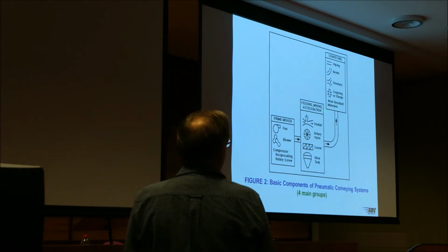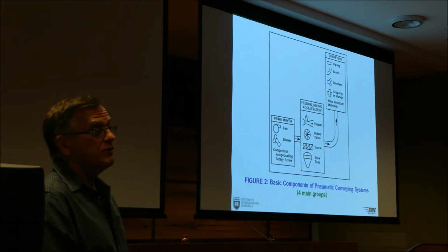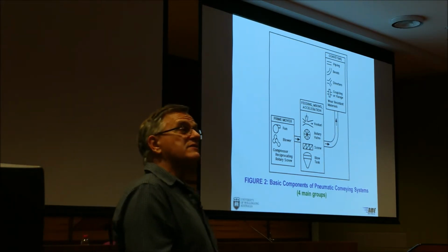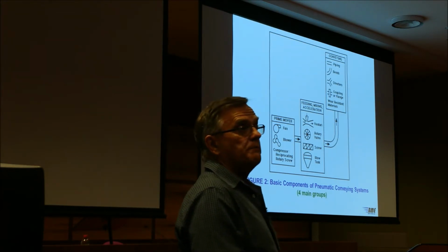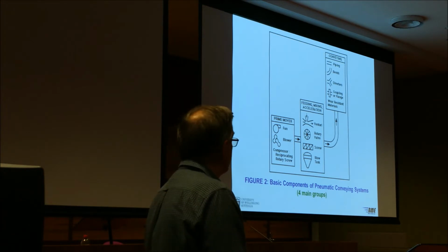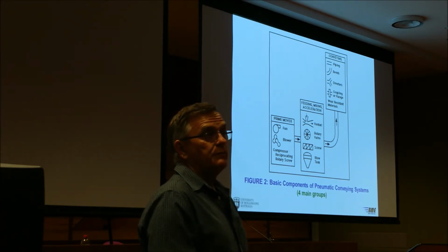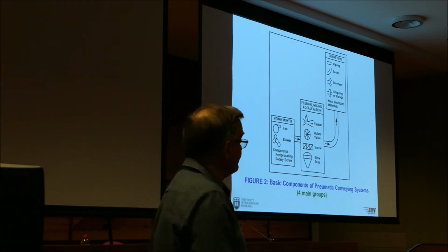If you've got abrasive products, we can purchase wear-resistant materials as well, not just mild steel. We can buy hardened steel, or you can buy basalt pipes. That gets very expensive and very heavy. But there's people go to these lengths to make their pipelines last the distance.